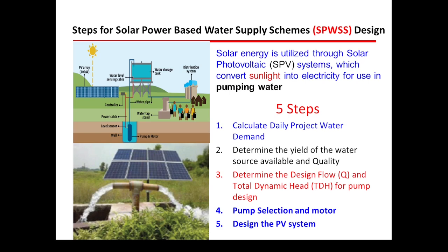What is the daily demand of the project area? Also, in determining the TDH, you should consider the static head, friction and minor losses, and also treatment equipment losses.